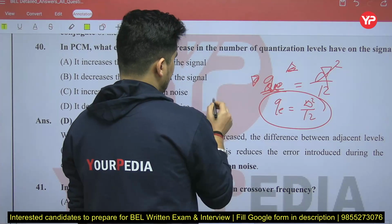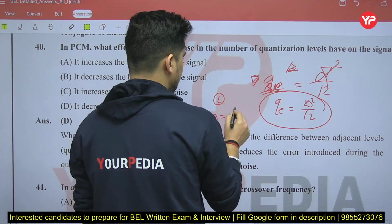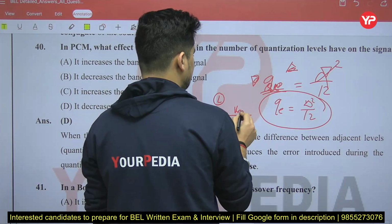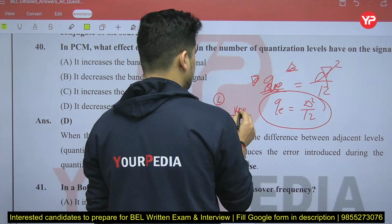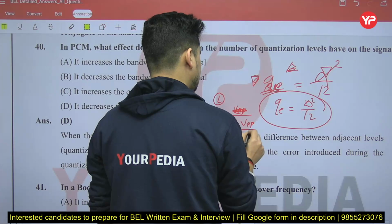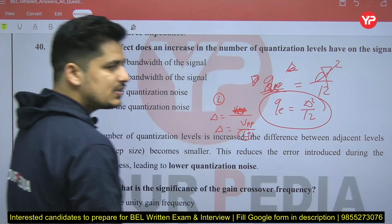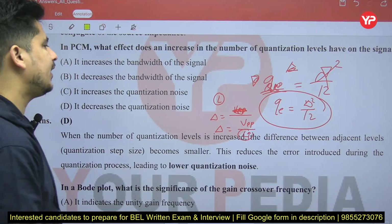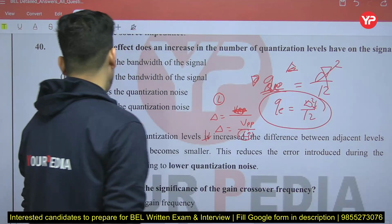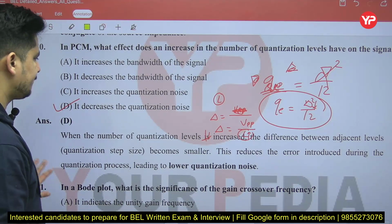So basically, if you increase the level L, the step size delta is equal to V peak to peak, not maximum, that is peak to peak, divided by L. When you increase the number of levels, your delta will decrease. When your delta decreases, your quantization error will decrease. So quantization noise will be decreasing.